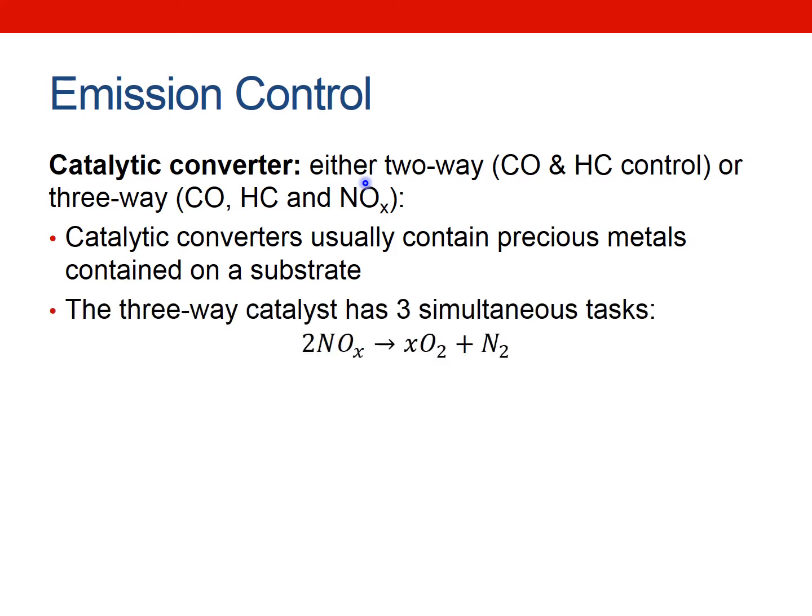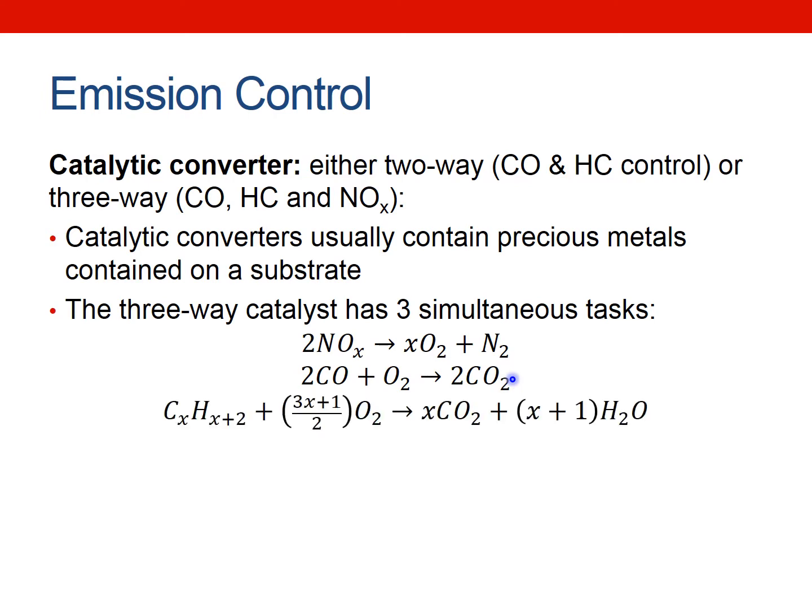And so what it does is it does three things. It will take your NOx and combine that with excess oxygen in the exhaust, giving you nitrogen. It will take the CO and completely oxidize that to carbon dioxide. And it will also take your hydrocarbon, whatever that may be, in this instance an alkane, and combine that with oxygen, giving you CO2 and water.